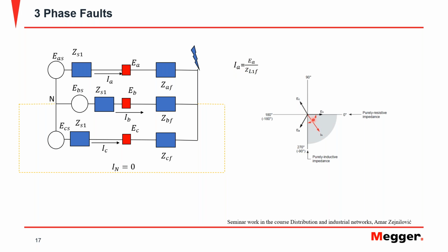So that means that for this case, we have a condition where we have the current. We represent the current here, lagging the voltage by an angle that in this case will correspond with the angle of the line. Since the line is mostly inductive, then the angle is going to be skewed and close to this axis here, because it's going to be very inductive.